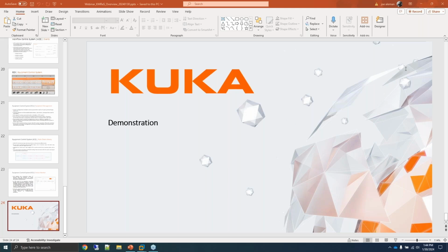Based on the location of the obstacle relative to the vehicle, it will try to find a path around first without moving, so that it doesn't start a motion and can't finish it. But if it starts a motion and can't finish, then it'll stop and be in an error state. If everything is correct and you have enough space to get around the obstacle, the vehicle will automatically go around the obstacle, come back to the edge, and then continue on the path.